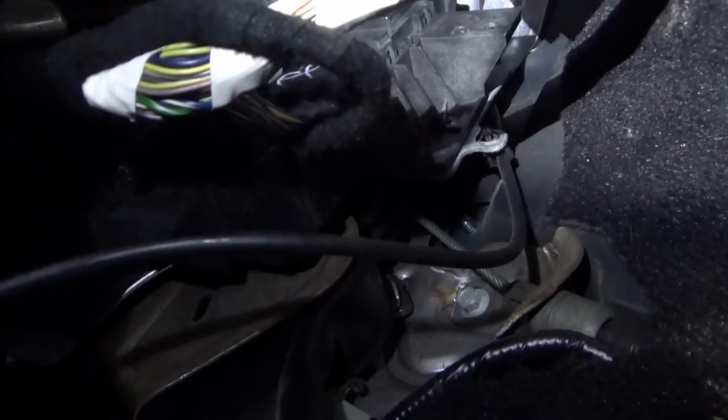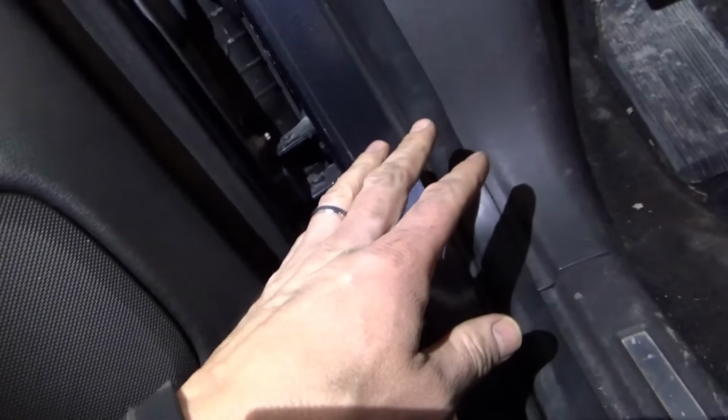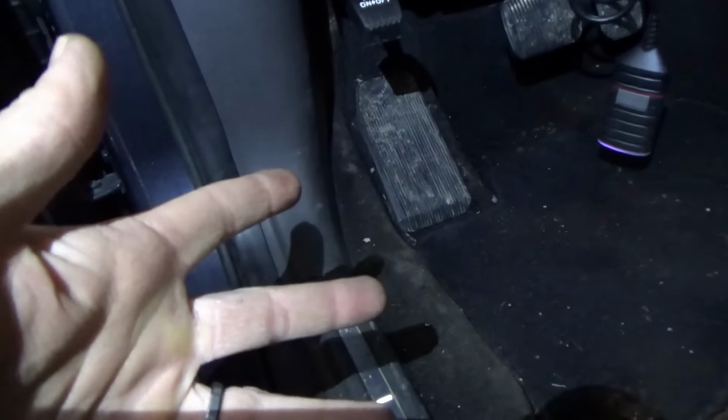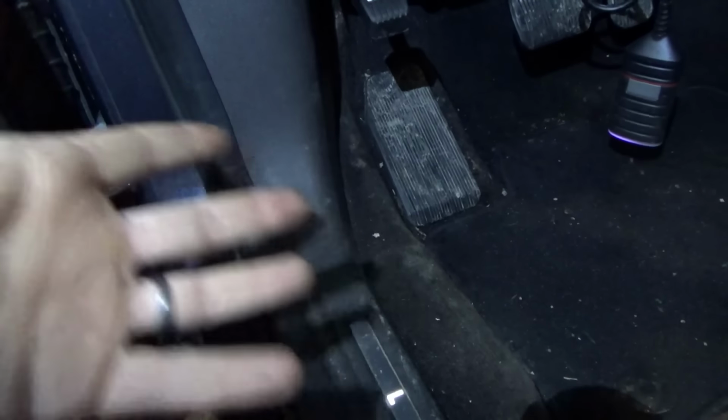And we see little rust spots, like this has been wet for a little while. So let me tear off this kick panel, lift up the carpet, see if there's any intermediate connectors that have been getting wet with the green crusties or something. This is a huge clue. So are we going to find the problem with the turn signals? Perhaps, but we'll see.